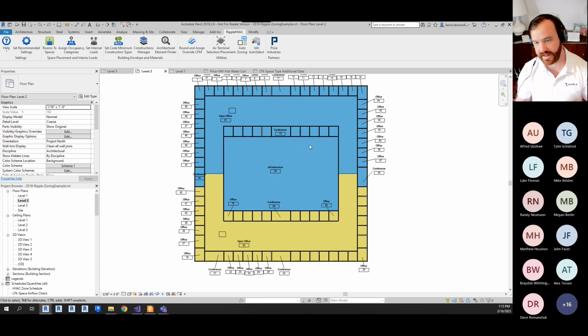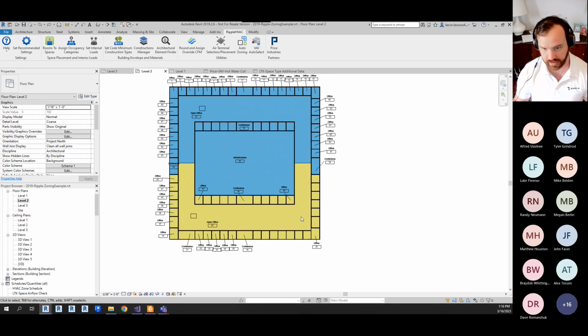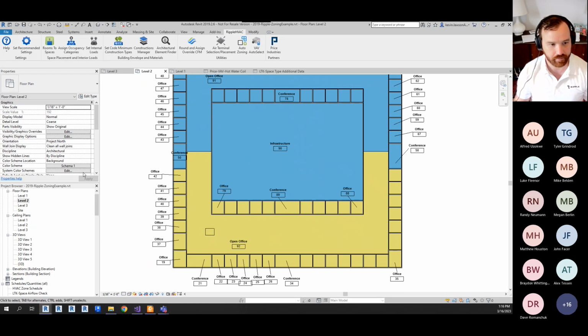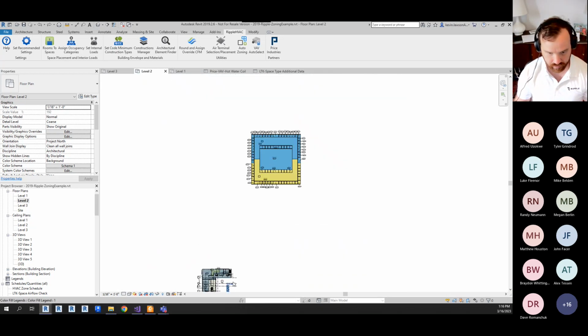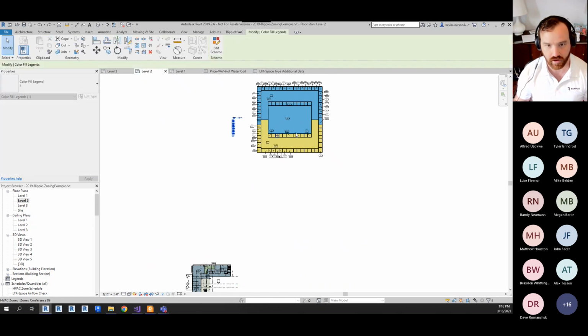You know, all things being equal, it's going to try to keep you on an east-west axis to get the most diversity out of your air handling unit. So, you know, sun in the morning here, these are going to be peak load, and then these are going to be peak load in the afternoon, so you get more diversity. But it just splits things up as equal in CFM as necessary. So this will be a little bit more exciting for the VAV auto zoning.